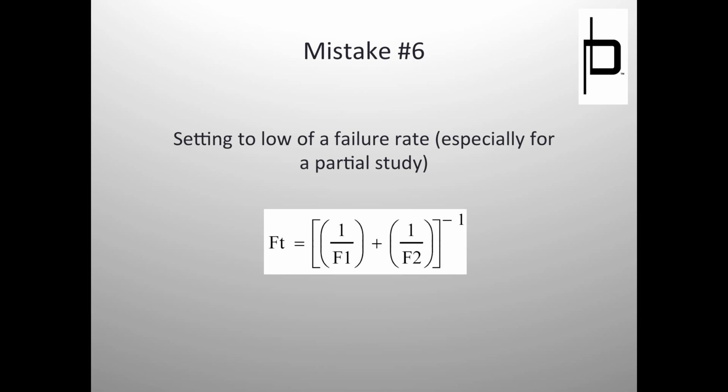So you violate your own design criteria, the only limit that you set, one failure every 100 years, whatever it is. So yes, think about whether this substation could expand. Anytime you do a major change to the substation, you should look at the whole substation again from a lightning perspective and see what the failure rate is now.